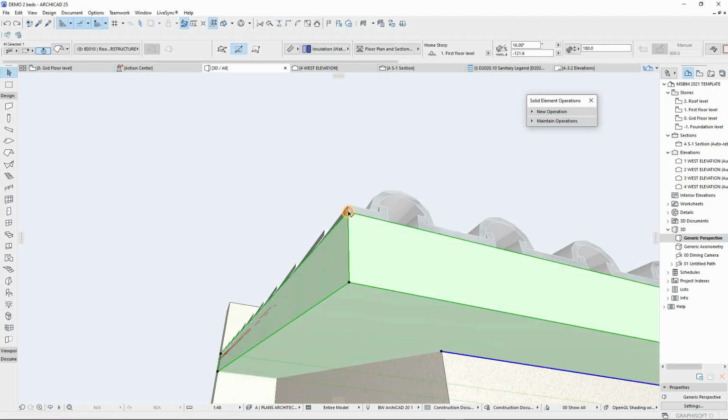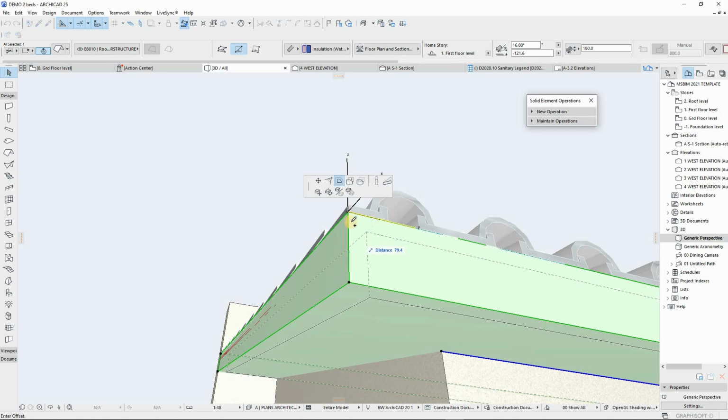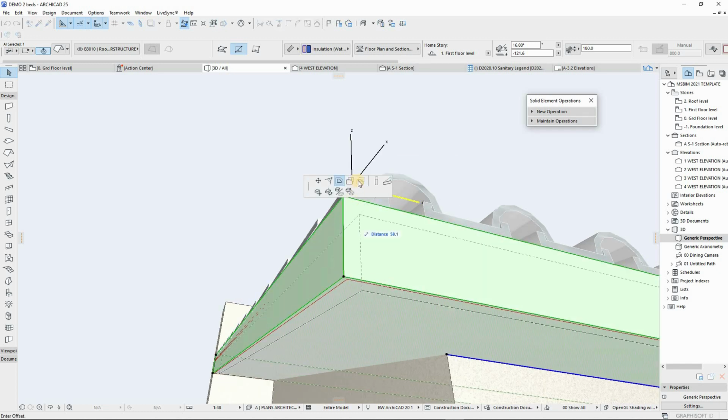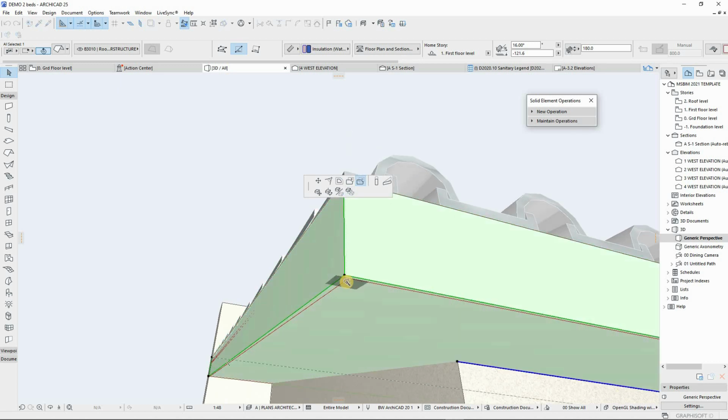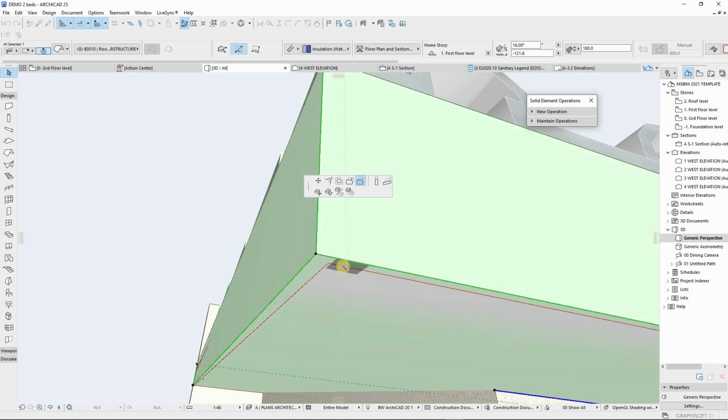We can also offset a copy. To do that, you click on the edge and then offset all edges, then hit Control on the keyboard to add a copy like that. Then I'm going to use the thickness of our fascia board. For the sake of 3D, I'll say 10. Perfect. And then pick this, subtract, and then hover, press and hold the shift bar to pick.